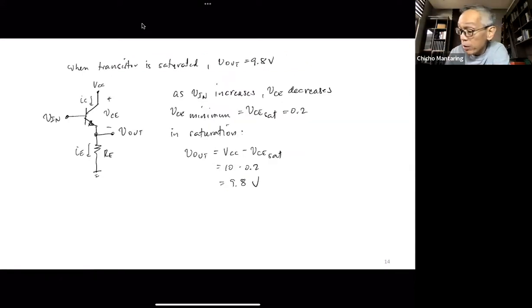This amplifier, we also call your emitter follower. Why is it called an emitter follower? Because the voltage at the emitter follows the input. Again, this is from the perspective of your AC input signal. Whatever the input is here, that is also the value of the output here. So the emitter just copies whatever it sees at the input and reproduces it at the output.